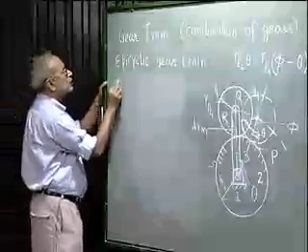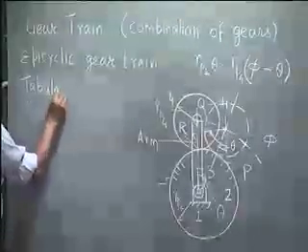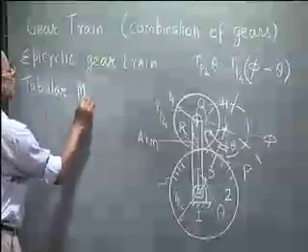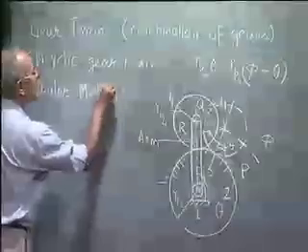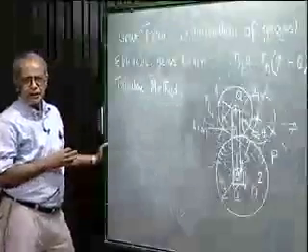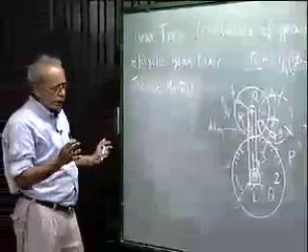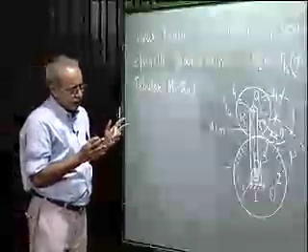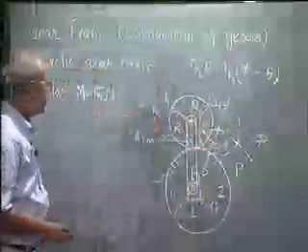What we will do, we first lock all the elements of a planetary gear train to the arm. All the elements are locked to the arm. That means the whole thing becomes one rigid body.